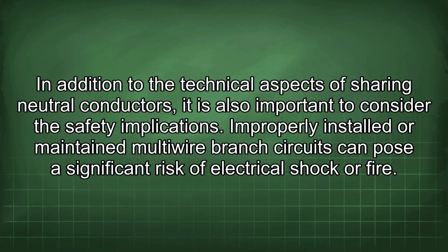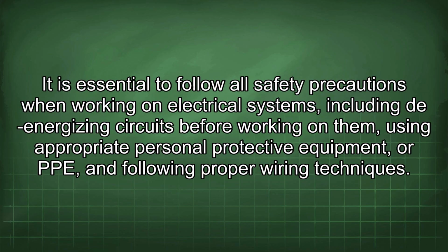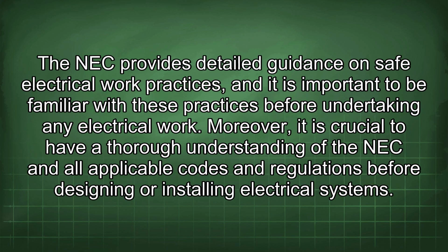In addition to the technical aspects of sharing neutral conductors, it is also important to consider the safety implications. Improperly installed or maintained multi-wire branch circuits can pose a significant risk of electrical shock or fire. It is essential to follow all safety precautions when working on electrical systems, including de-energizing circuits before working on them, using appropriate personal protective equipment, or PPE, and following proper wiring techniques. The NEC provides detailed guidance on safe electrical work practices, and it is important to be familiar with these practices before undertaking any electrical work.